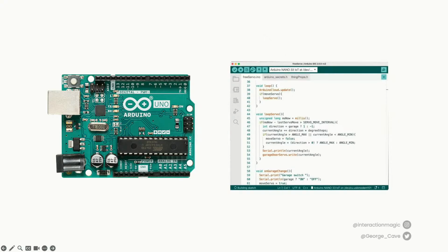You download this free piece of software on the right, which is the IDE, but it's also a kind of compiler and upload tool. So you write some C or C++ in this, and then you upload that code onto the Arduino, and that code will live on that Arduino and run the same way no matter where you take it. Each of these little numbers is a pin you can connect something to, like a switch or a light or a sensor. That's all there is to it.